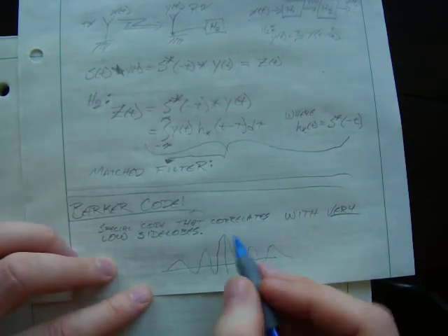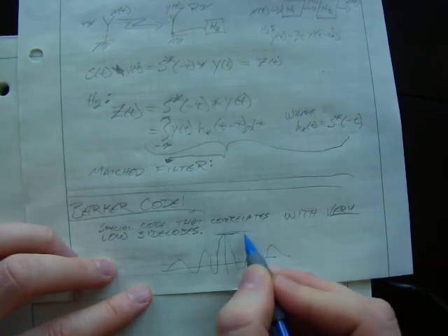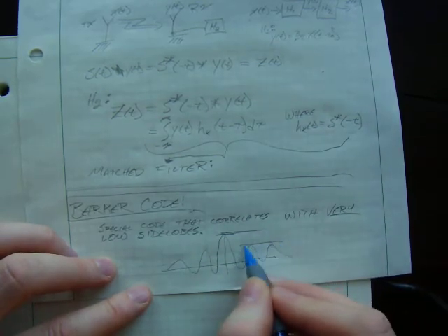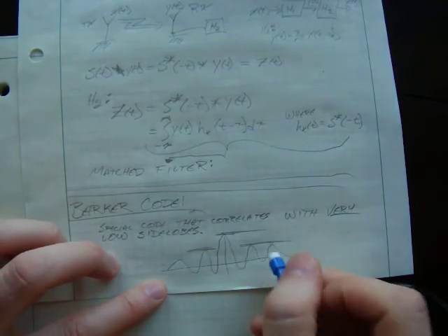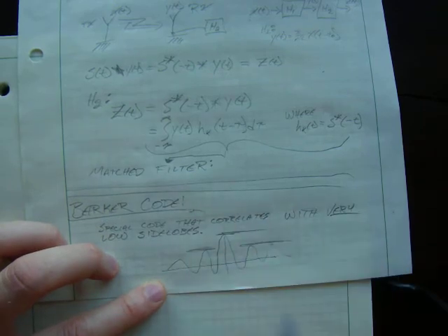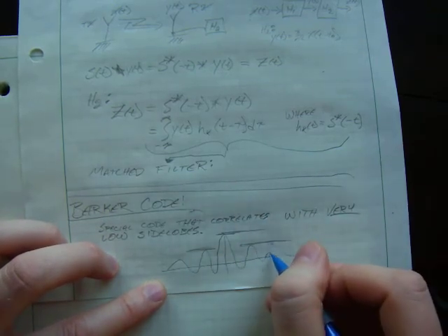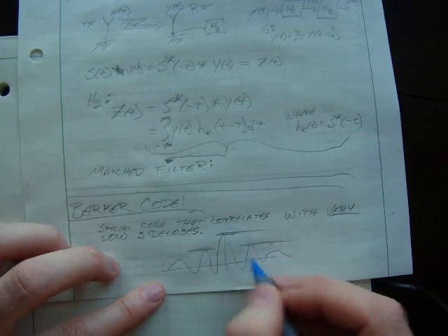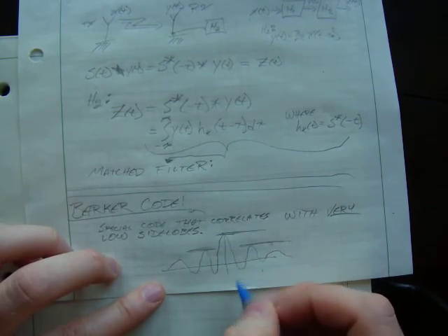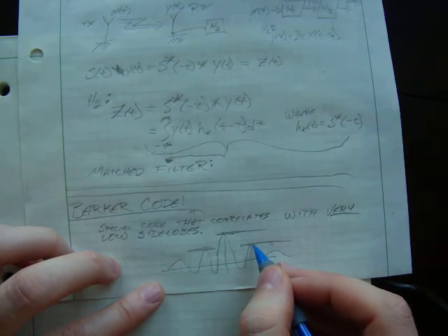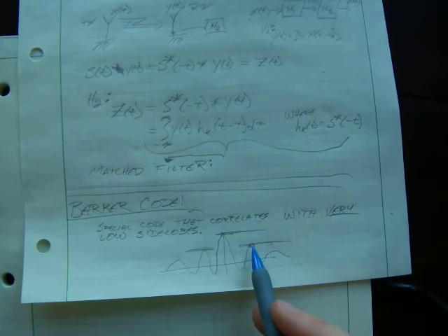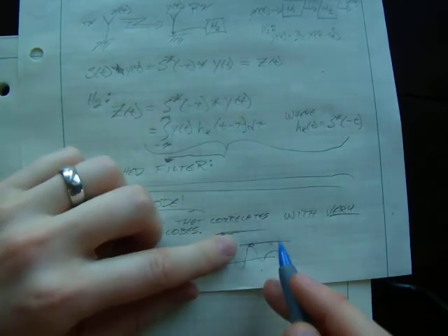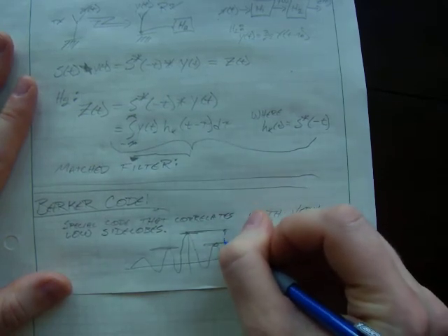When we're looking at side lobes, this is the main lobe, and this is the side lobe. Usually the side lobe right next to the main lobe is going to be the highest, because there's correlation right after it nulls out. This is the thing we're trying to minimize. Depending on the type of signal, there are a lot of different optimizations that can go on. A Barker code optimizes this.